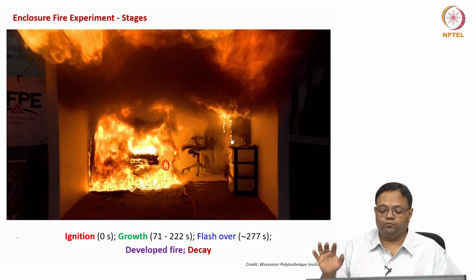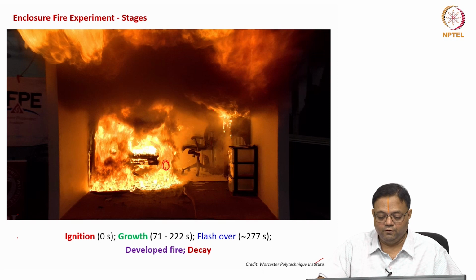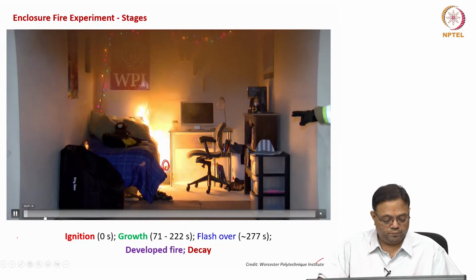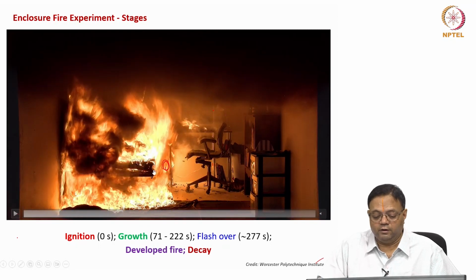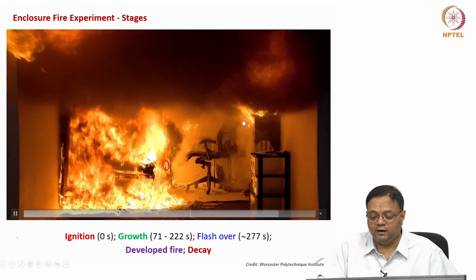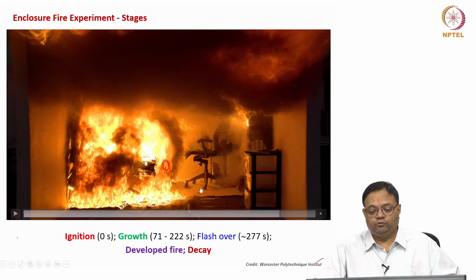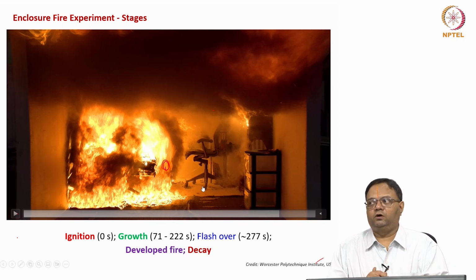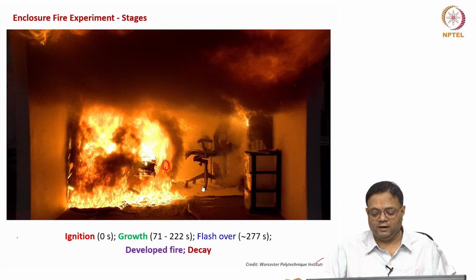The flashover actually occurs only when the temperature of the smoke has reached a particular value which can radiatively heat the commodities. So that means here in this case, I will go to this particular point. Here this big fire is not able to ignite them. Only the smoke layer temperature, because of separation distance basically, after a particular point you can see that the ignition occurs because of the smoke becoming hotter and hotter. So flashover, one of the thumb rules what we saw was the smoke layer temperature reaching a delta T of 500 Kelvin plus. So that has caused this.